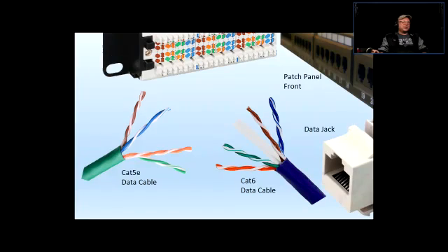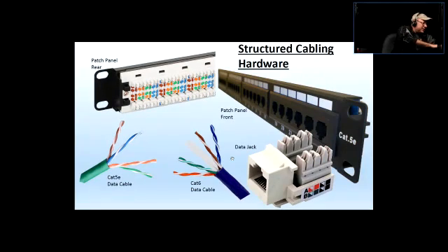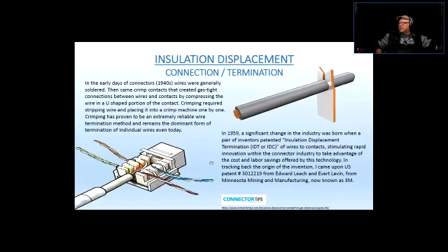The main reason for having a twisted pair is to eliminate interference from other pairs and crosstalk between the pairs. Crosstalk is basically a signal bleeding from one pair to another. And this is a Cat5e cable, which also has a twisted pair, but it doesn't have that separator. So now you know the difference between Cat5e and Cat6, and Cat6 and up, basically.